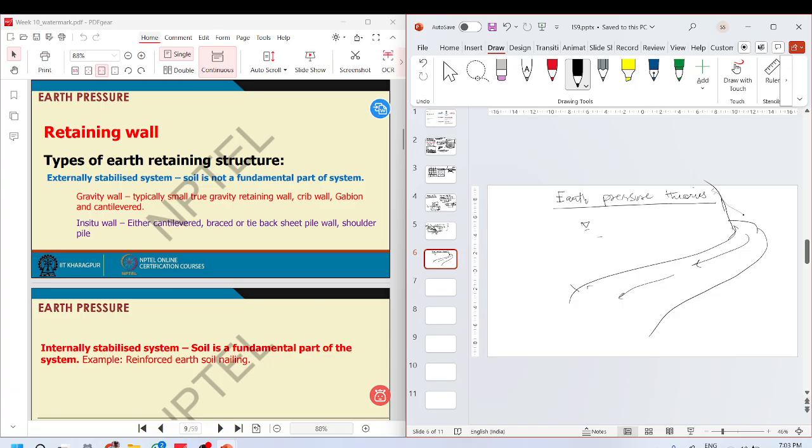It used to be like this, and now you have removed this soil and made a steep cut here. All the load from above can lead this slope you have created to fail and just fail like this.